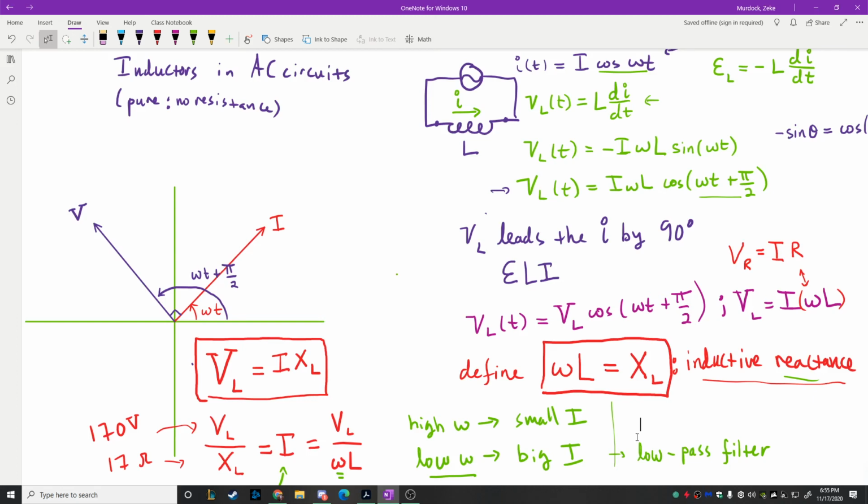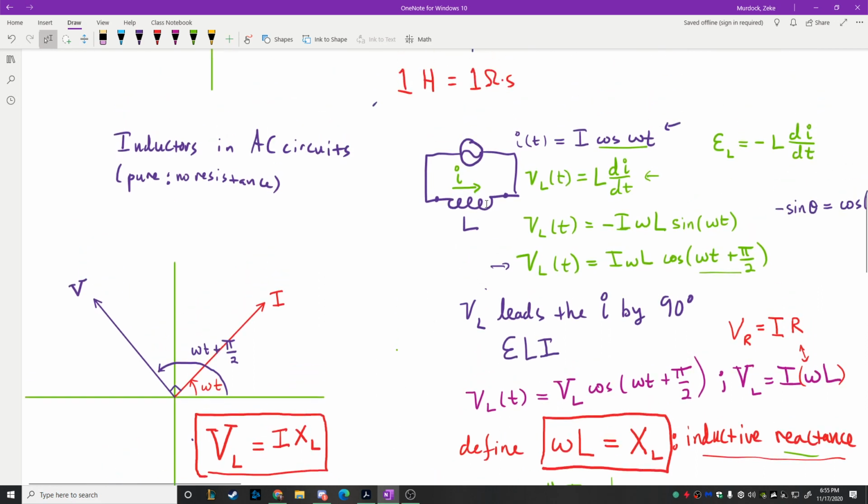Yeah, there you go, Jesus, yeah. So if anybody has any experience with being in someone's car where they really turned up the bass, literally at its core what's happening is the inductance of the circuit is being changed. And how that's happening could happen in various ways. Someday you all will be engineers and you'll be very good at manipulating these kind of things. But it could involve taking a piece of iron and moving it in and out of the coil to variably adjust the inductance. It could involve disconnecting certain coils of it by some kind of a rotor that moved around it and only connected half of it to the circuit, anything like this.